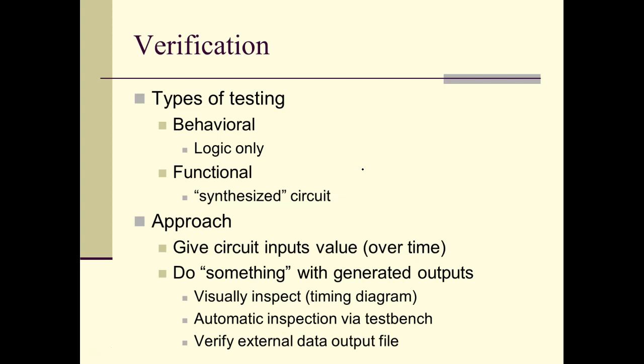You can view this as a two-step process. I'm going to get my design to work behaviorally, and then I'm going to move over to functional testing. Essentially, that's testing of the synthesized circuit, and you'll see, particularly in Vivado, there are all sorts of different testings. The idea is when you drop this on an FPGA, it has all sorts of routing issues, and it's placed and routed automatically for you. It does the best it can, but there are going to be issues with it, particularly as you bump the clock speed of your circuit up.